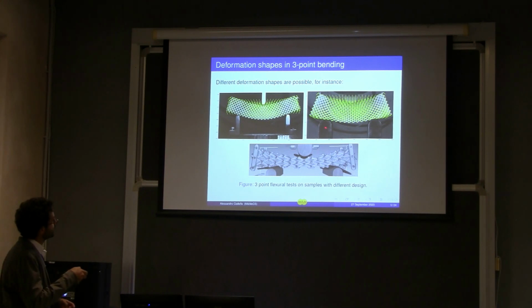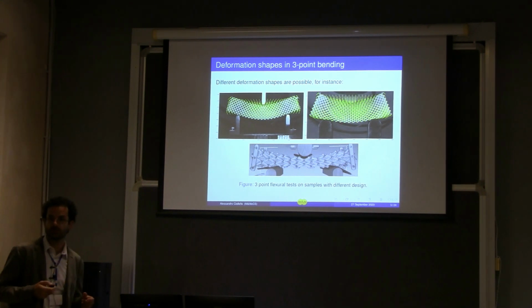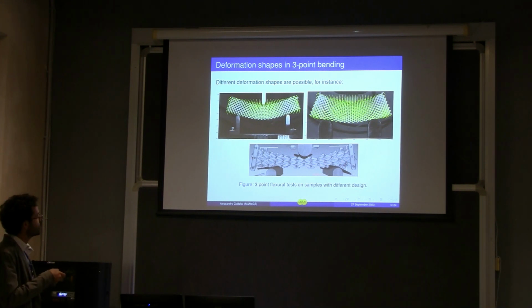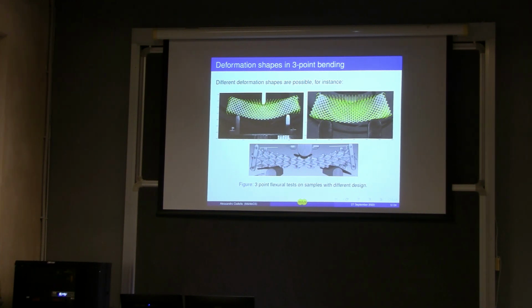In this case, instead, we have a more flat bottom surface of the specimen, and an S-shape bending of the beams is activated. In this third case, the one that Professor Dell'Aquila was also talking about in the previous presentation, we have essentially a flat bottom. So we were curious about possible deformation shapes and what are the features that trigger different behaviors.